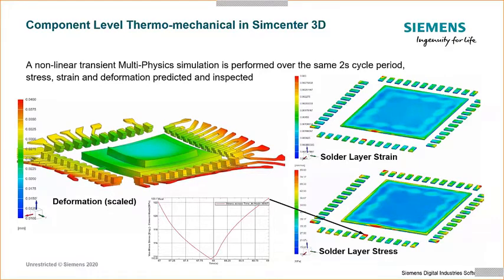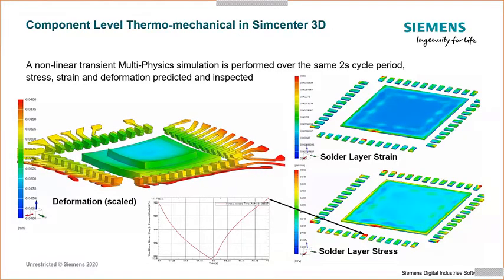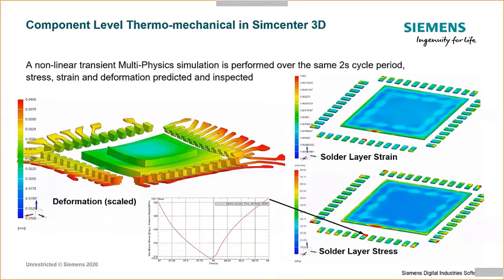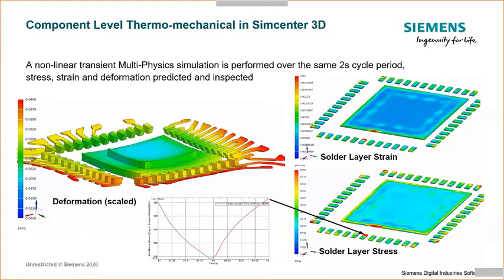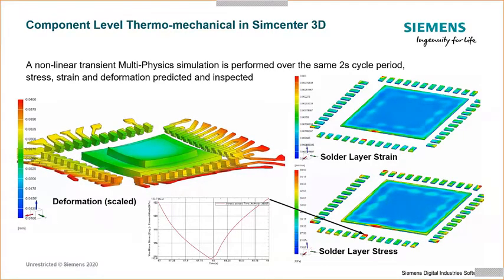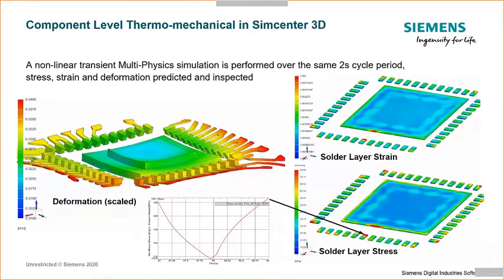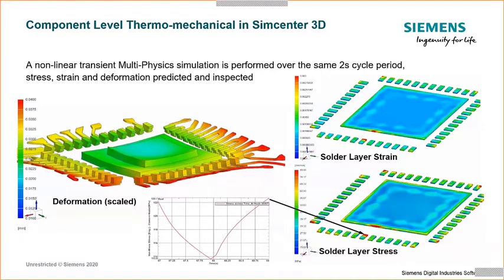The strain and stress can be inspected. For example, we can plot a variation of stress or strain versus time for that one cycle. Actually, although not shown here, if we plotted stress against strain for this one cycle, then the area of the hysteresis loop would represent the strain energy, the energy that contributes to damage.